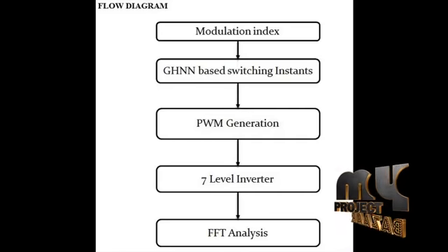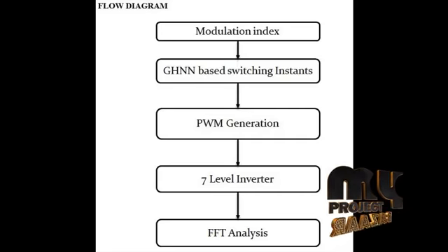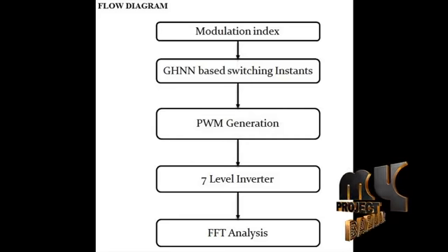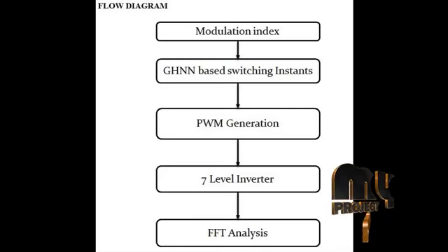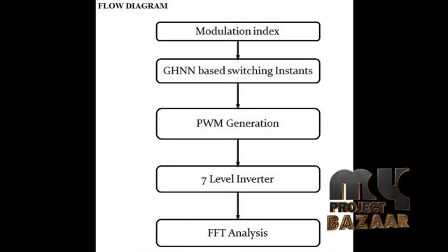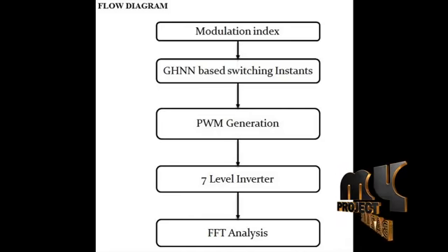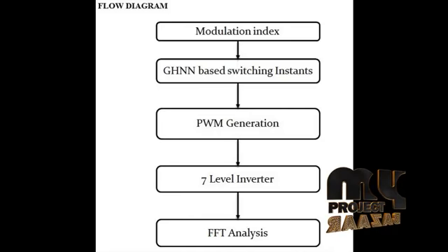Modulation index: it is the ratio of the fundamental output voltage to the DC input voltage. Generally, it is the ratio of the reference signal to the carrier signal. So the amplitudes of the reference signal and carrier signal are compared using this modulation index.